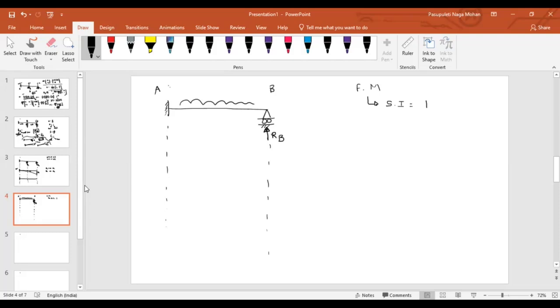We have already discussed why this is useful, because solving things for a cantilever beam is easier, right? Now, what is the next thing we should do? As we are talking about displacement compatibility, first of all, remove this support. If you remove the support that you have taken as the indeterminacy, how is it going to deflect? This is the deflection at point B due to applied loads. After that, what do you have to consider? You have to consider the reaction at B.